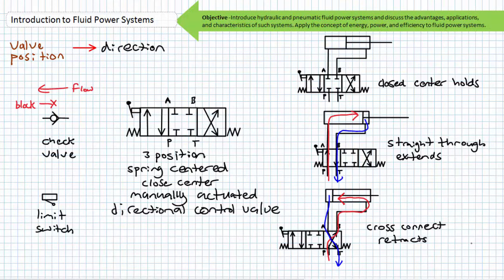In addition to operators manually monitoring and operating fluid power systems, consider electrically controlled fluid power systems that automatically monitor position with the use of mechanical limit switches, magnetic proximity switches, and position transducers that output a voltage or current signal proportional to position. Automated systems do not necessitate constant human supervision.